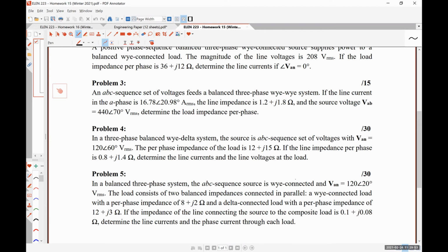The lighting loads and all that kind of stuff are purely real. So generally speaking, you try to make sure that you have as much lighting on one phase as the other. It's literally just, let's try to make things as equal as possible. There's always going to be some little amount of imbalance, but as long as it's not too bad, things are generally okay. So did that remotely answer your question?